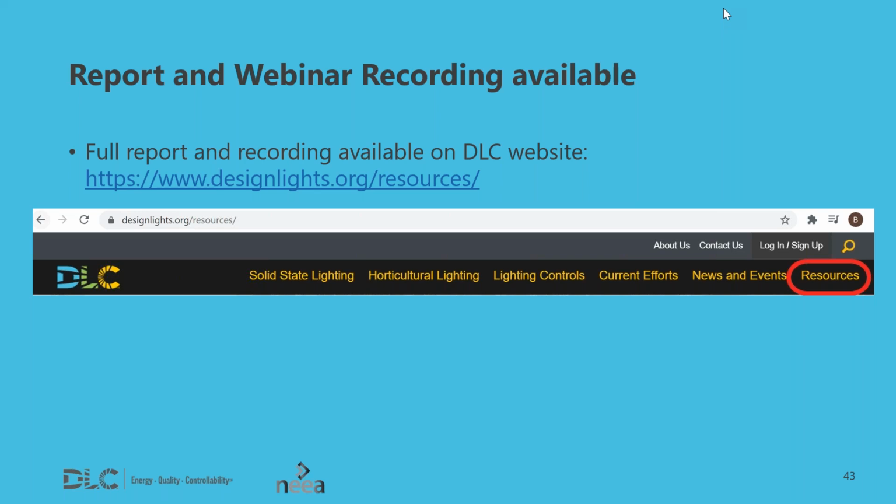For, again, my opinion, control persistence to a utility is vastly important, because what that basically says is that if the system loses connectivity to one or more of the sensors or one or more of the fixtures, it is not going to revert to an all-on mode. It's going to revert to an energy efficient mode. So from a utility's perspective, control persistence is highly sought after, because we don't want to see these systems not save the energy that we are counting on them to save if they're not connected correctly or there's something going on inside the system.